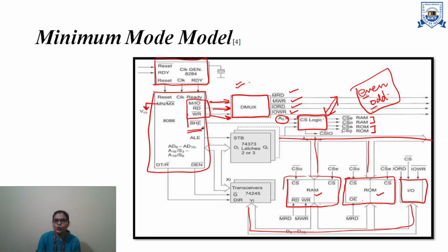These two pins will drive the chip selection logic, which will select the even and odd banks of a particular memory.